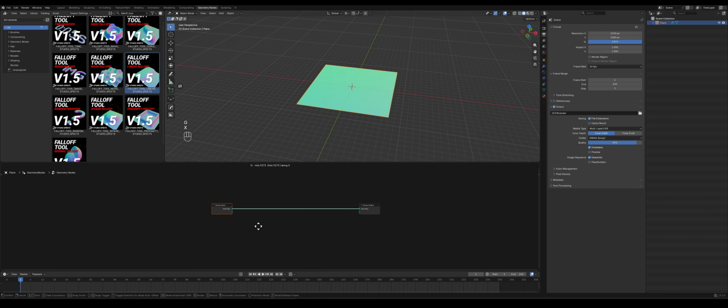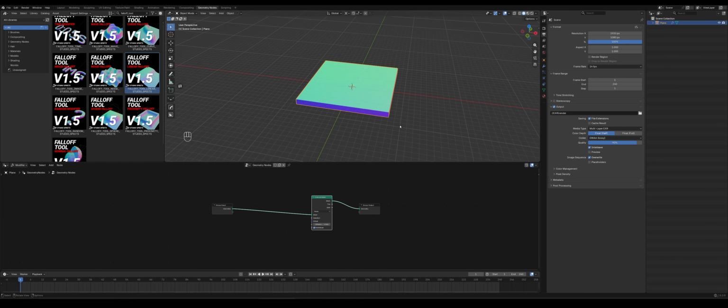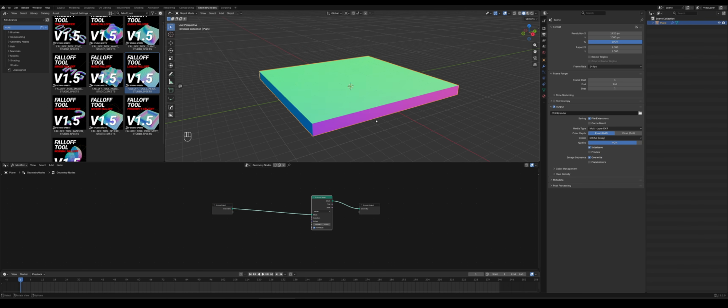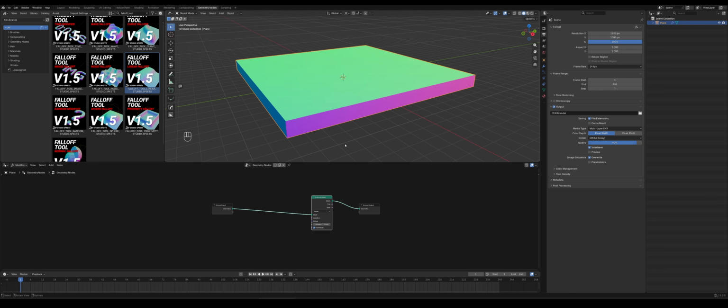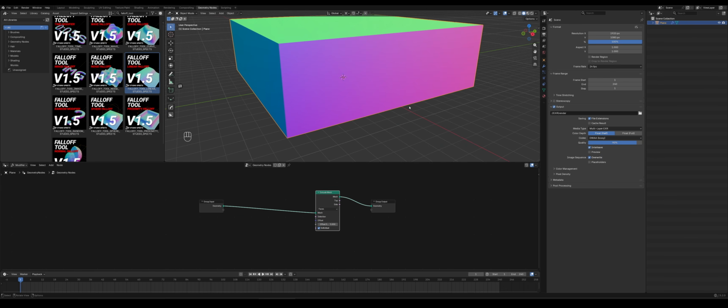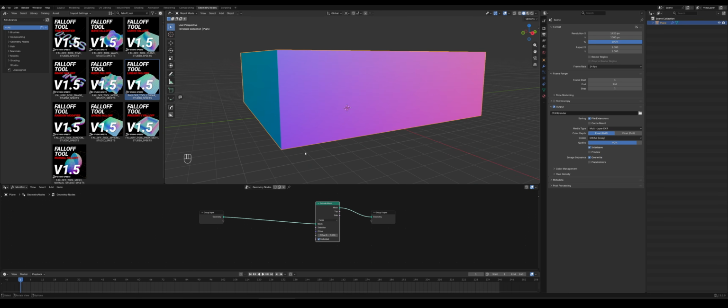So we have this geometry node setup right here, and in order to make it a staircase, I'm going to extrude this plane. So I'm going to extrude the mesh so we get some height in there, because a set of steps or stairs, of course, go upward. So let's set it, I don't know, up to 5. We all know that stairs, of course, gradually go up, and we can use a linear falloff for that.